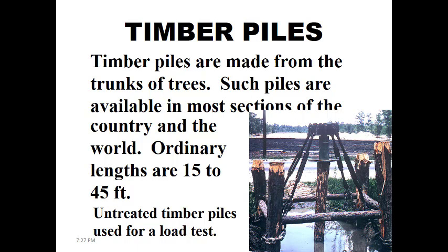So the lengths can vary significantly from one project to another, even from one location in the same project to another, and it all will depend on the soil analysis, soil data. So you realize that the range from 15 to 45 feet is really big, and if you think of a pile as something that you need to drive into the soil, it can be really challenging to have this 45-foot long stick and something like a hammer at the end hitting it and driving to nail it down.